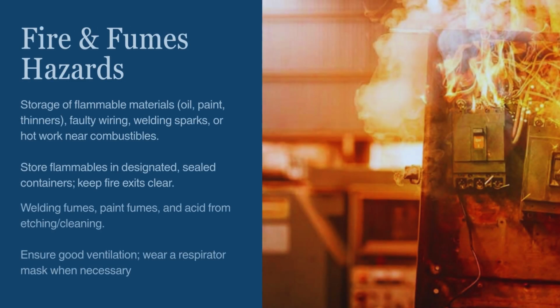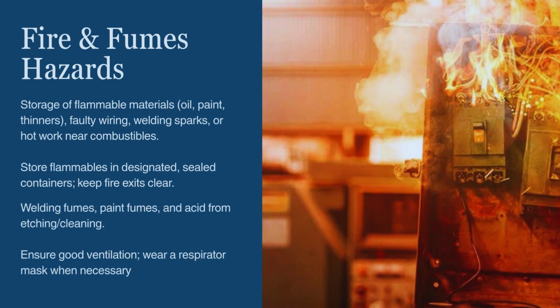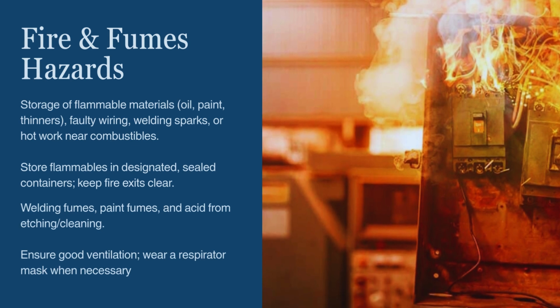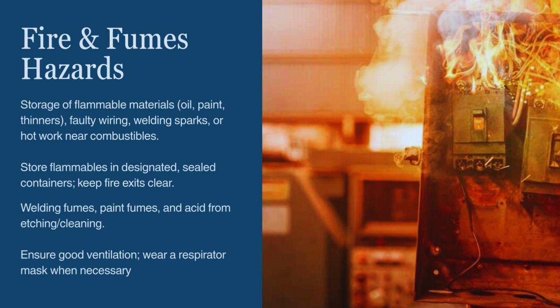We now move on to fire and fume hazards. These are common in workshops where heat, sparks, or chemicals are present. Sparks from welding, cutting, or grinding can ignite flammable materials such as oil, solvents, or fuel. In addition, welding and certain chemicals produce harmful fumes that can affect your lungs and overall health. Always ensure proper ventilation, keep flammable materials stored safely, and make sure fire exits are clear at all times.